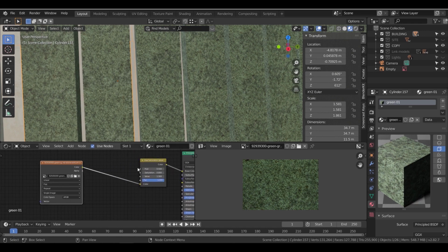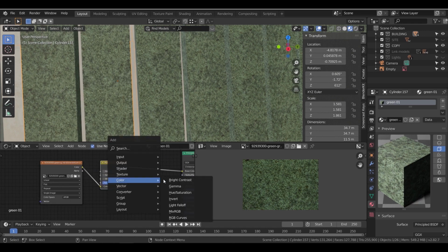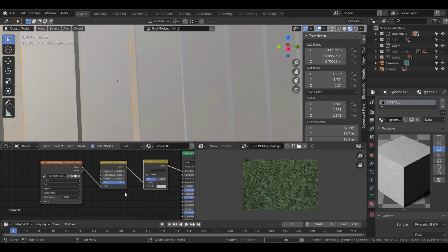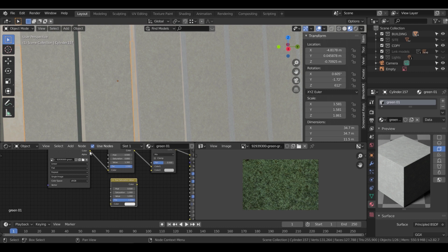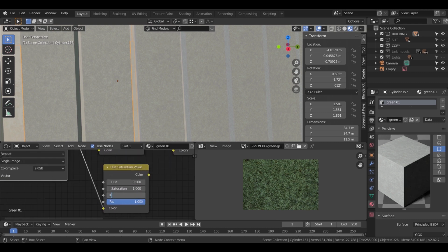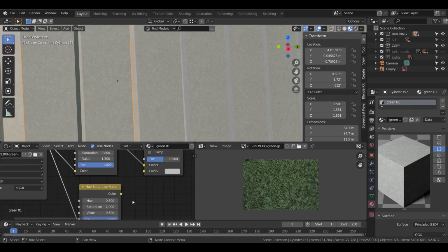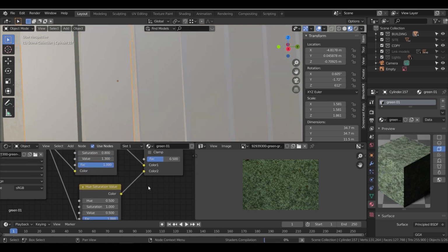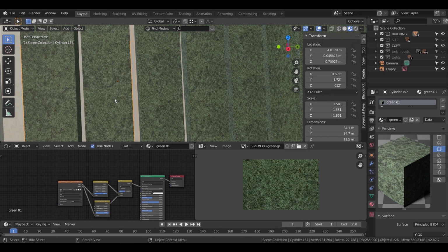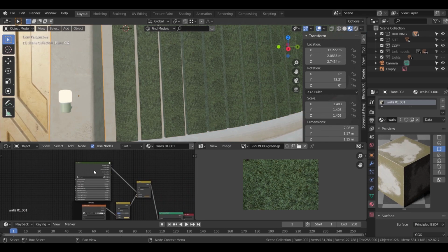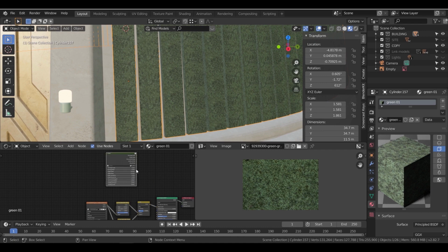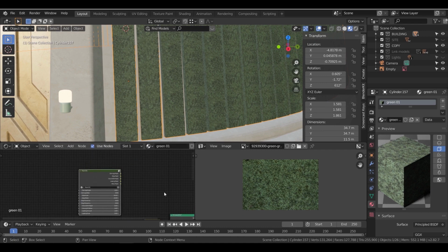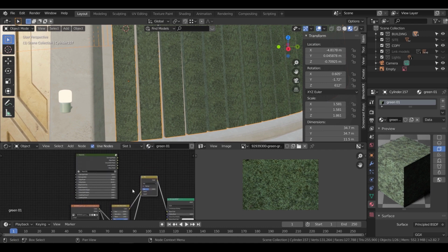We also need a color mix node for the dirt mask, so add it here, in the second color of the mask, the one that would appear as dirt. We will have a different hue saturation node connected to it, and make it a bit darker with the value number as shown. Now, bring the mask node here, however, this time, we will take the ground dirt mask, and connect it to the mix factor.